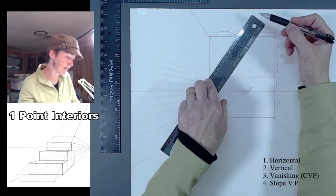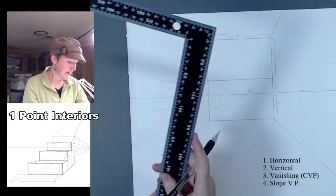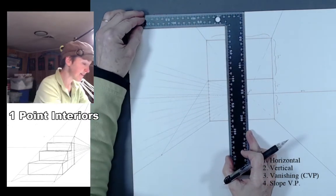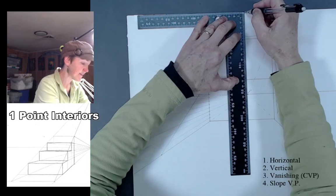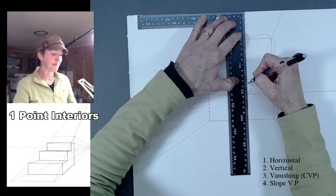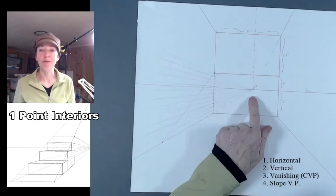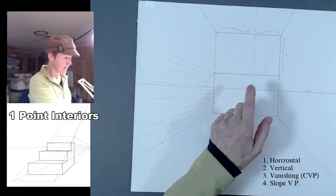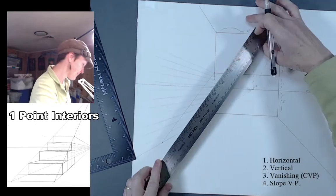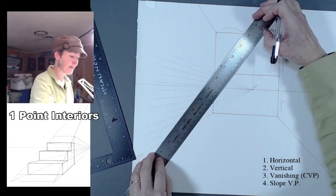So maybe I'll find the straight line first to make sure what I'm aiming for. I'm using a framer square to make sure that's really a nice vertical line. And this is one of those exceptions where you may have some diagonals that don't lead to your central vanishing point, but it's still leading to a measuring line. So we'll be extending this slope of the steps up until it hits that dotted line that we just drew, that's straight above our vanishing point.